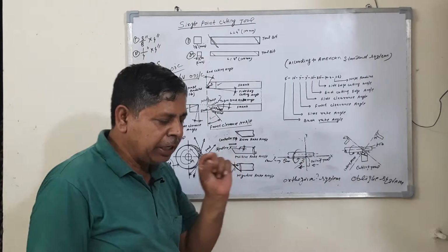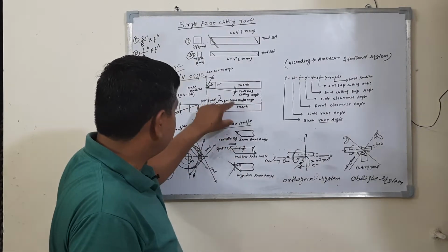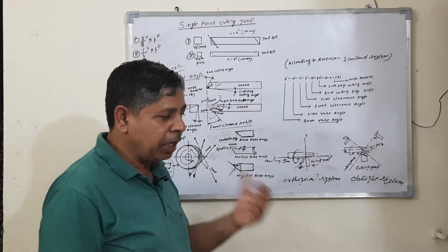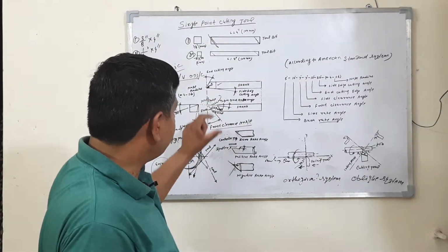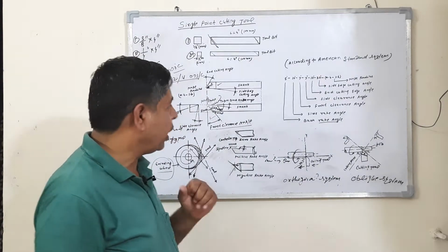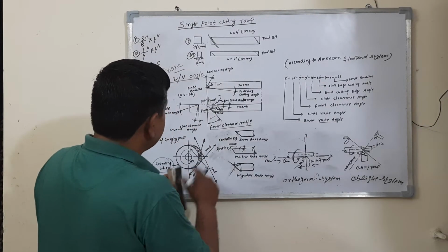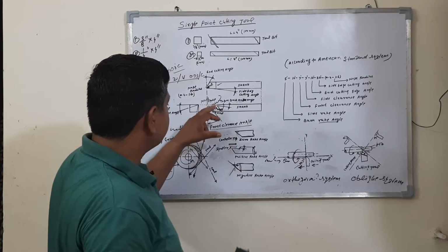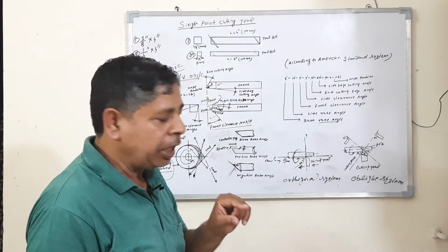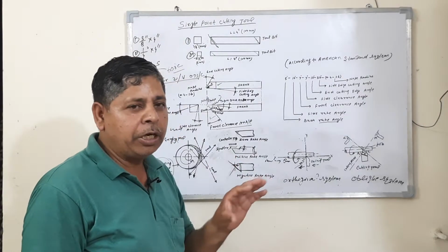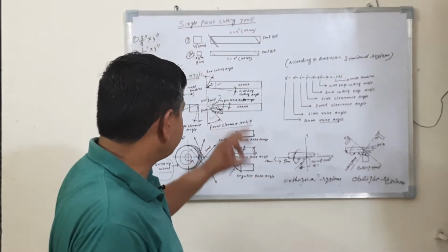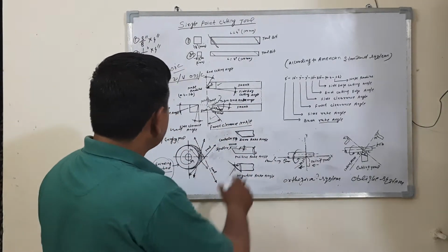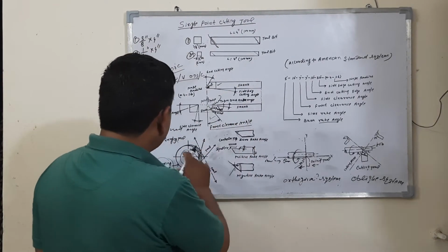If the rake angle is low, the depth is low and the speed is high, to get good accuracy and also control the tool life. If this angle is increased, the area is also increased. It means the depth of cut is very high and the speed is very low. You cannot get a good finish on the workpiece if the rake angle is increased. These angles are performed by the grinding wheels.